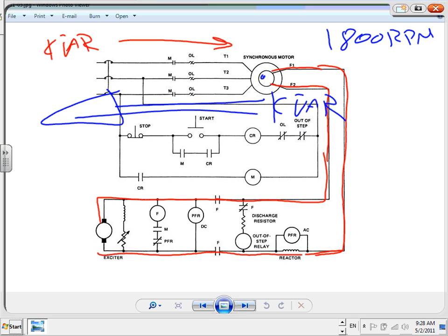Except the synchronous generators, they're pumping what? They're pumping power. These guys are not pumping power, they're pumping kVAR. They're doing the same thing, except you can't use this kVAR to run a motor. You can use it to kill the bad news of a motor, which is the inductive reactance. Any questions, guys, about this? Synchronous motor, unloaded, overexcited, solves the problem of your bad power factor.